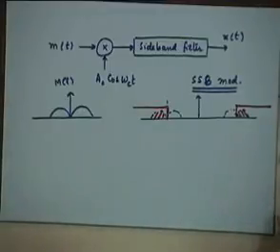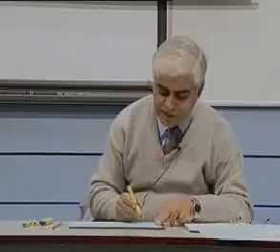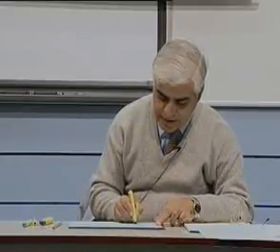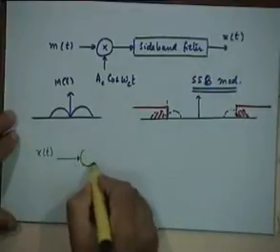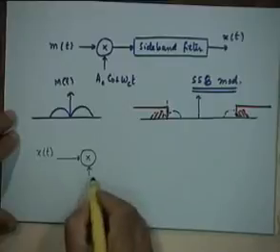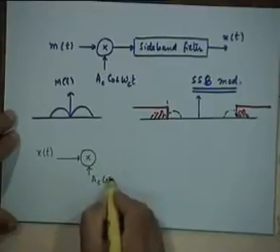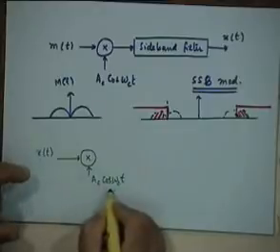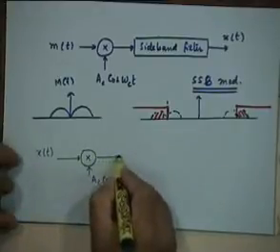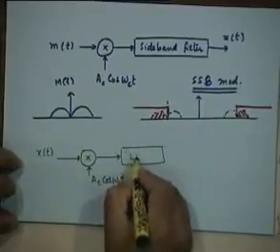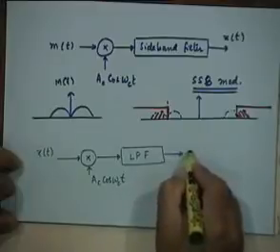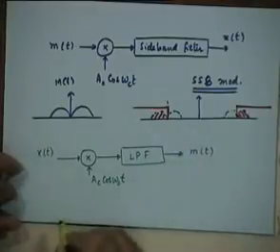The demodulator remains the same synchronous demodulator that we had for DSBSC. Absolutely no difference. Convince yourself. So what I'm saying is, as far as the demodulation is concerned, take your modulated signal x(t), multiply it with a coherent carrier which is in phase and frequency synchronism with the incoming carrier, and pass it through a low pass filter, and you will get your message signal back. Is that obvious?